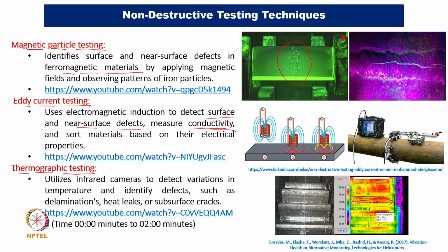We mentioned also that thermographic testing is very cost economic. It gives a whole surface in one go, and we can get a kind of idea of what problems there are, but going into fine detail we really require a lot of filtration, a lot of post processing. If we have those kinds of software available or good cameras, we can go ahead with thermographic images or thermographic testing. However, if we want only a glimpse of what kind of faults there are and where the fault is located, that is also possible. In this case, we are showing here a gear that has a lot of flaws, and we are able to show the thermographic image.